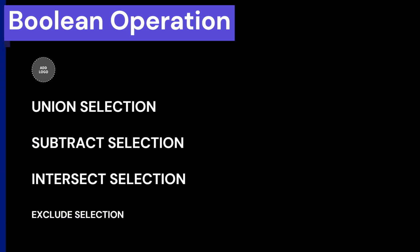So let's look at Boolean operation. Boolean operations are union selection, subtract selection, intersect selection, and exclude selection. With those operations, you can combine two elements, subtract from two elements, intersect selection between two elements, and exclude elements. These are elements like shapes.